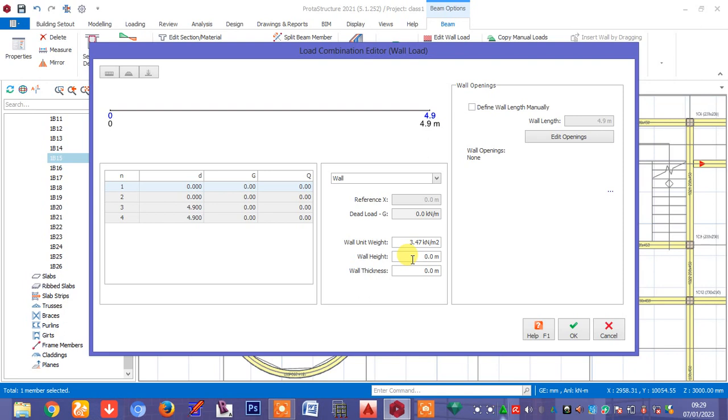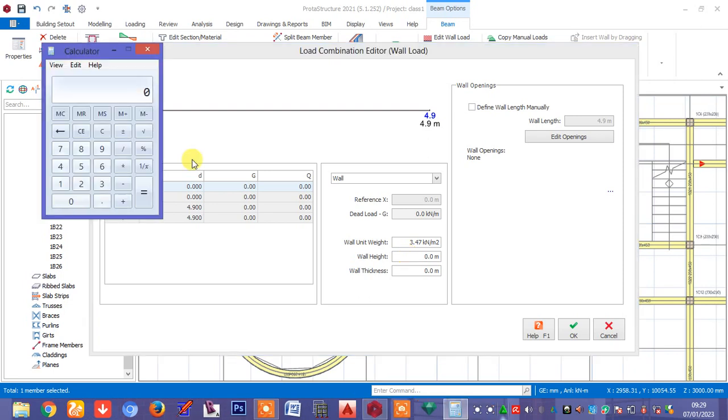So if we're using a beam depth of 450, assume the height of our building from the architectural design is 3,000 millimeters, that is 3 meters. Then minus the depth of your beam, which is 450. The 450 is including the slab, because the slab is 150. The depth of your beam alone is 300.